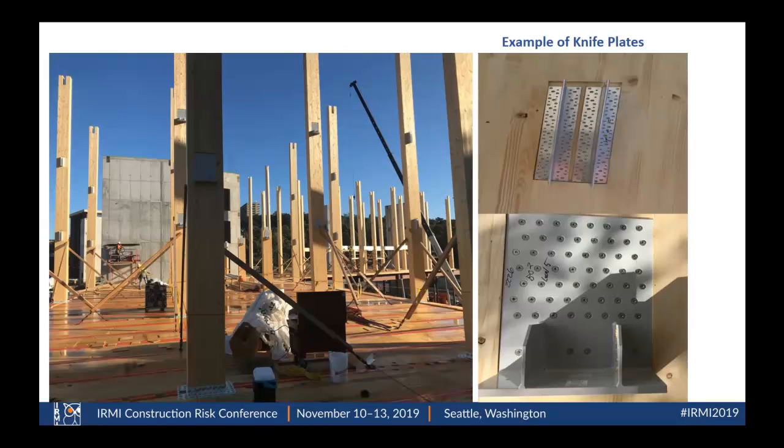That served for water on the surface, not allowing it to go through and stain the bottom side of the CLT, and also kept the gypcrete from seeping out. A gypcrete topping went on top of that. At all the columns, we taped them up with something like a flex flash like you'd use around a window, a Trimco flex flash, to keep water from running down the face of those and staining them.